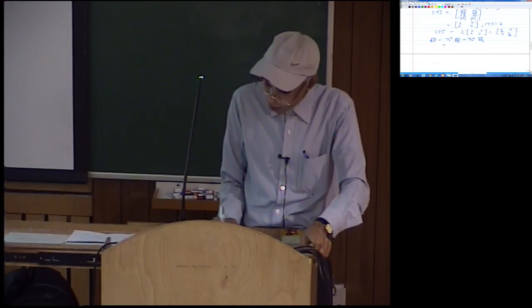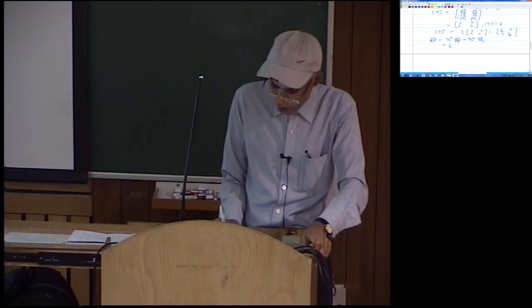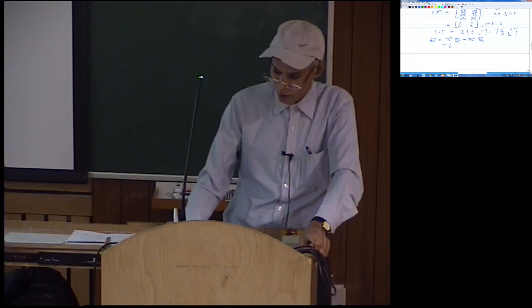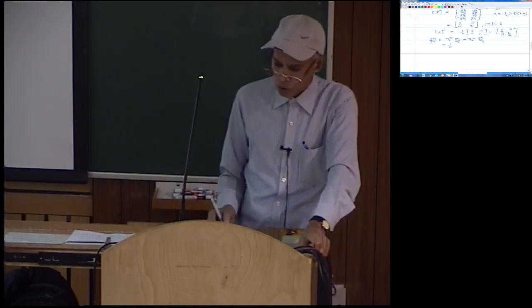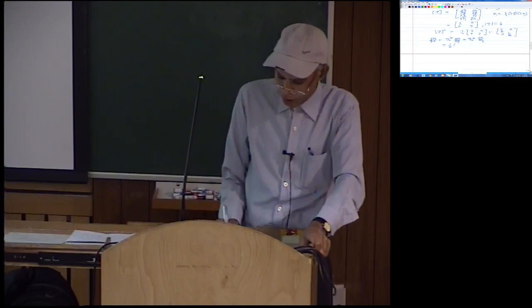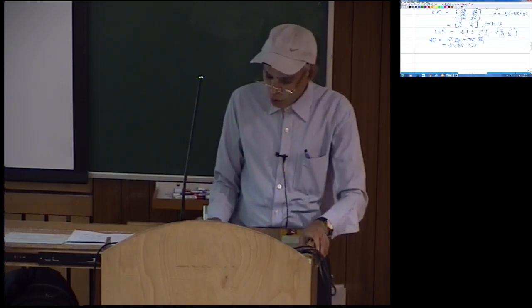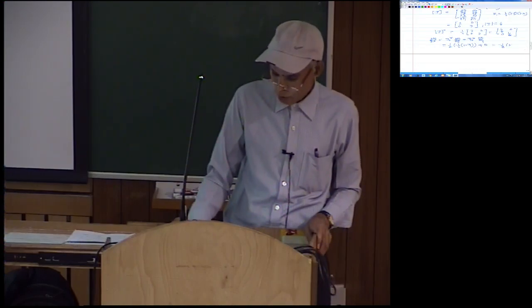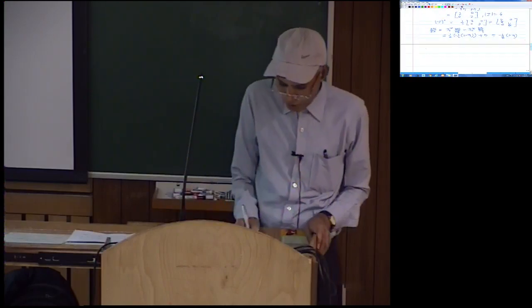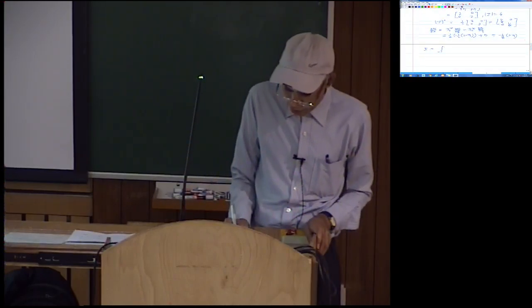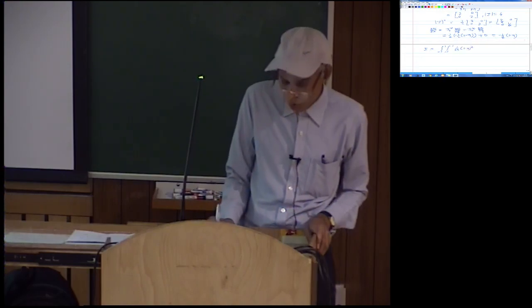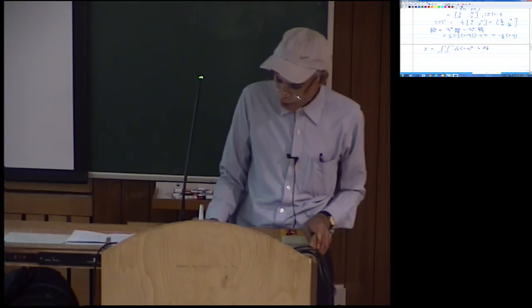So here J11* is 1/2, into ∂N1/∂xi. The expression for N1 is 1/4 into (1 minus xi) into (1 minus eta). So ∂N1/∂xi is simply minus 1/4 into (1 minus eta). Since J12* is 0, we don't worry about that. Now you put all of this in the integral. So that is the integration from minus 1 to plus 1, minus 1 to plus 1, of 1/64 into (1 minus eta) squared, times the determinant of J, which is 4, d xi d eta.